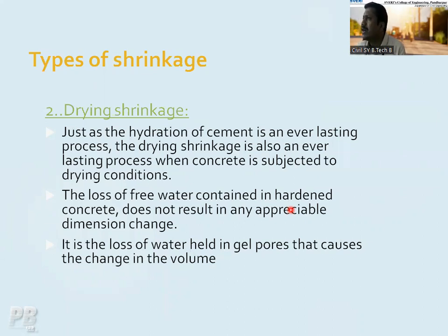What is heat of hydration? Heat is liberated from that concrete body. Very simple. There is formation of the CSH gel and all that. So heat is being liberated during this process, and it's a continuous and long lasting process. Everyone knows it. And along with that, there is drying shrinkage which is also going to happen if you are going to keep your concrete in the drying conditions.